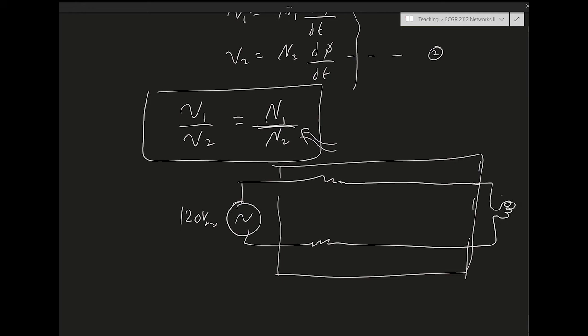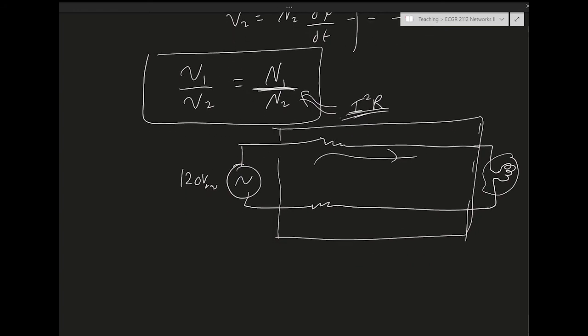So what happens is that you can deliver the power to the load, but the current passing to the load is passing through those resistors. So your I square R losses represent energy that is lost in transmission, energy that is not reaching the load and doing useful work. It's like an energy tax that you have to pay just to transmit the energy. Because the losses in transmission lines are purely ohmic, meaning they depend on the current, the P loss is proportional to I square R, right?